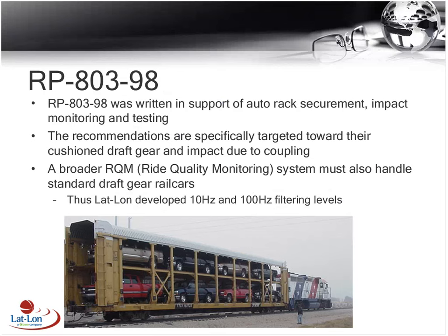803-98 was written to support the auto rack projects, and basically when you're worried about ride quality monitoring, the AAR is assuming that you're in a cushioned car to begin with. Otherwise, why go to all the trouble of worrying about impacts when you don't even have the right draft gear on the car? So the 10 hertz is a nice kind of slow number. It's not as aggressive as it could be for these cars because the squishy draft gear on them allows the events to take quite a bit of time, relatively speaking.